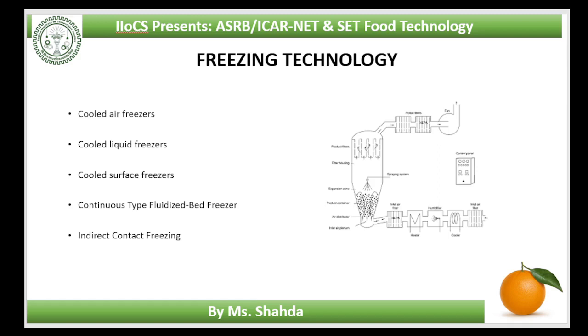Cold stores: ice formation on the floors, walls and evaporator coils is caused by moisture from the air or from unpackaged products in the store. This condenses to water and freezes on the cold surface, which reduces the efficiency of the refrigeration plant, uses up energy that would otherwise be used to cool the store, creates potential hazards from slippery working conditions and falling blocks of ice, and requires frequent defrosting of evaporator coils.